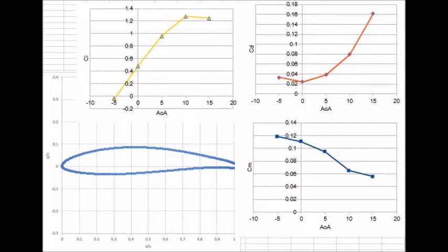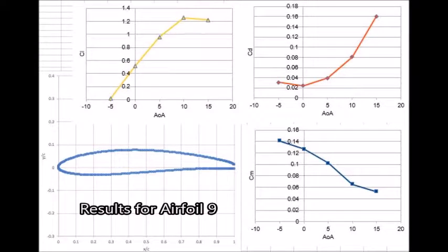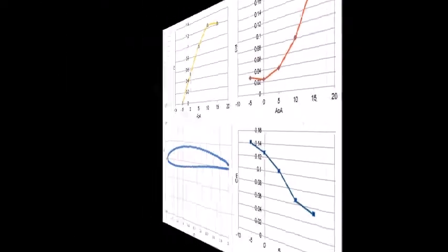In aerodynamics, things are non-dimensionalized, so these coefficients represent a ratio and are unitless. As you would suspect, the lift and drag coefficients represent the lift generated by the airfoil and the drag it experiences, respectively. The pitching moment deals with the moment caused by the aerodynamic force at the aerodynamic center. Once graphed, this data will be useful in predicting stall, which is the point at which increasing your angle of attack no longer provides you any more lift.